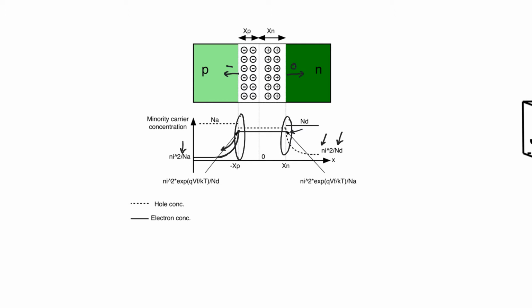This is an equation that deals with what happens to current if we pass through a region where there is excess recombination or excess generation. We're talking mainly about this area and this area, where the excess carriers that have been injected are being absorbed in the neutral zones. So let's talk about the n side, for example.